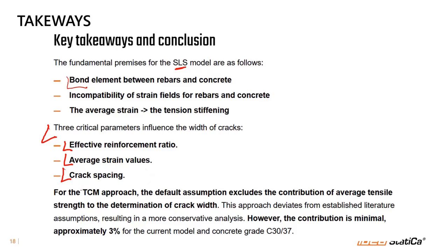And for the tension chord model, as I was mentioning, the contribution of average tensile strength, this epsilon cm, is neglected for the calculation inside IDEA StatiCa.